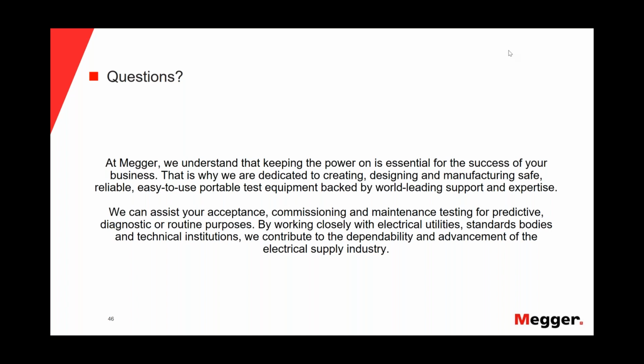Well, we have to distinguish between factory testing and field testing. The factory testing establishes a minimum acceptance criteria for the quality of the splice termination. So they do factory testing. They say, okay, it has to be below a certain level to be acceptable, because how long is this piece going to be out in the field? It's not out there for 1 year. It's probably on average out for 30 years.